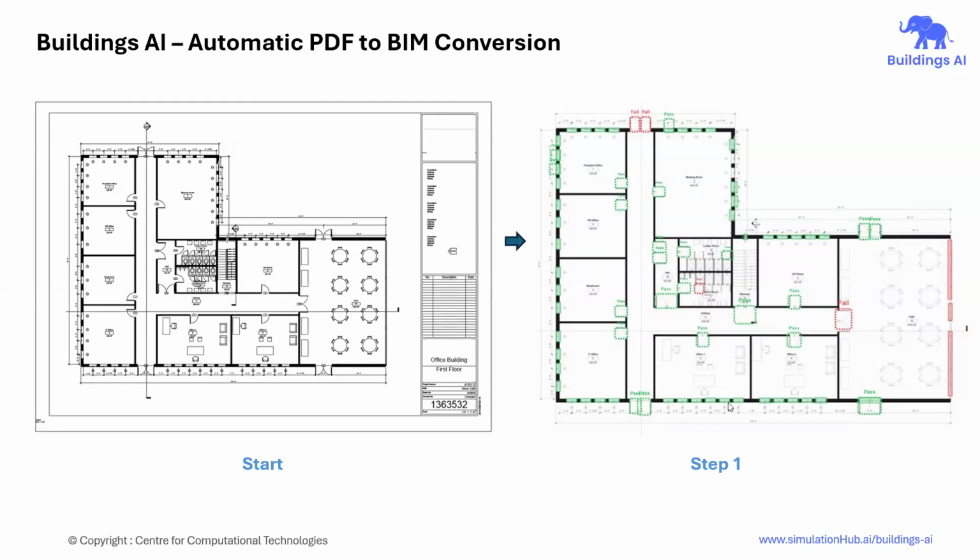The internal spaces will be filled with zones and spaces, and it will be extruded into a 3D BIM model. There are some red detections also, which means the user has to manually insert a door or a window there to complete the closed box BIM model.